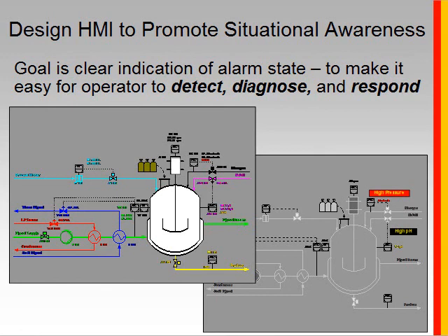You can see that the HMI screen on the right, where we've got two alarms in their own unique colors and blinking, draws your attention much better than the one on the left, where my attention is drawn to the blinking devices, as well as to the colors of the different piping and not to the alarms.